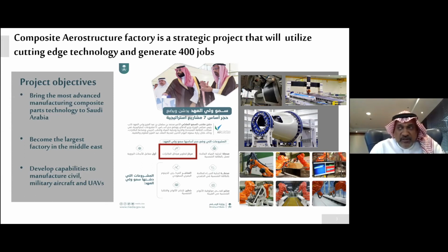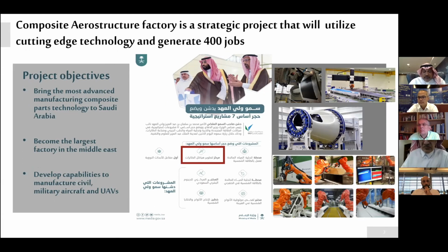Also, there's an autoclave, 10 meters long by 7 meters in diameter, for curing the composite part. And when I say composite carbon fiber, it's really thermoset. If you want to go to a thermoplastic with these machines, you have to change the head and do some modification to accommodate thermoplastic, but it's not there yet. I think as a business we need more thermoset.